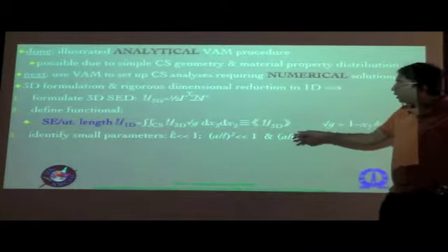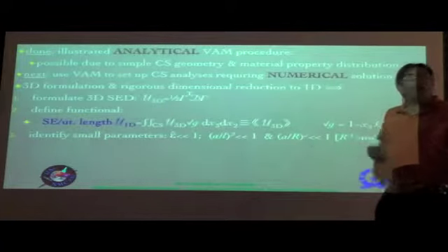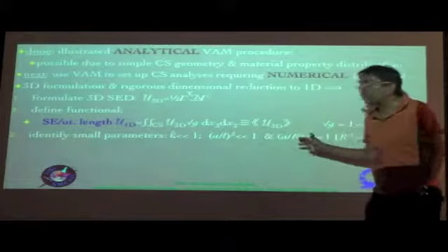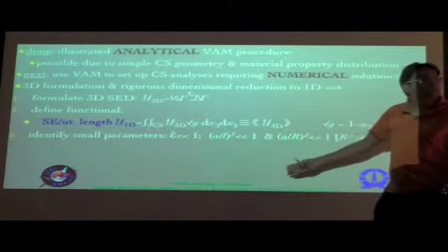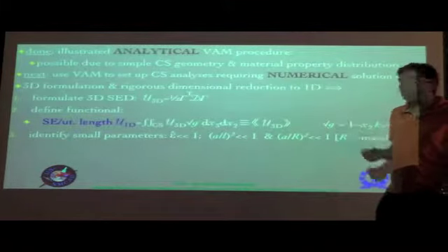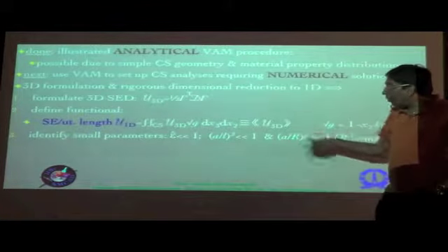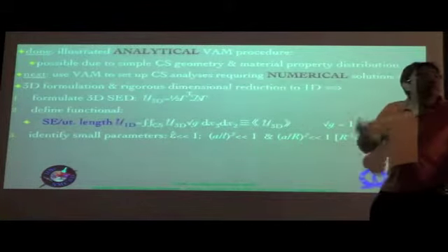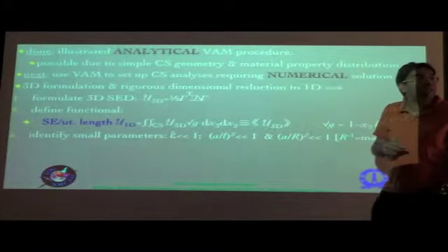But even in a case where you do not have, for example, any initial curvature, it's a prismatic beam where R tends to infinity, so L is obviously not of the order of infinity, but still you can make a special case out of the method that we develop here to drop off the terms associated with the curvature, and then you would end up with that situation as well. The problem comes only when R becomes smaller, so that basically it becomes a very small initial radius of curvature.